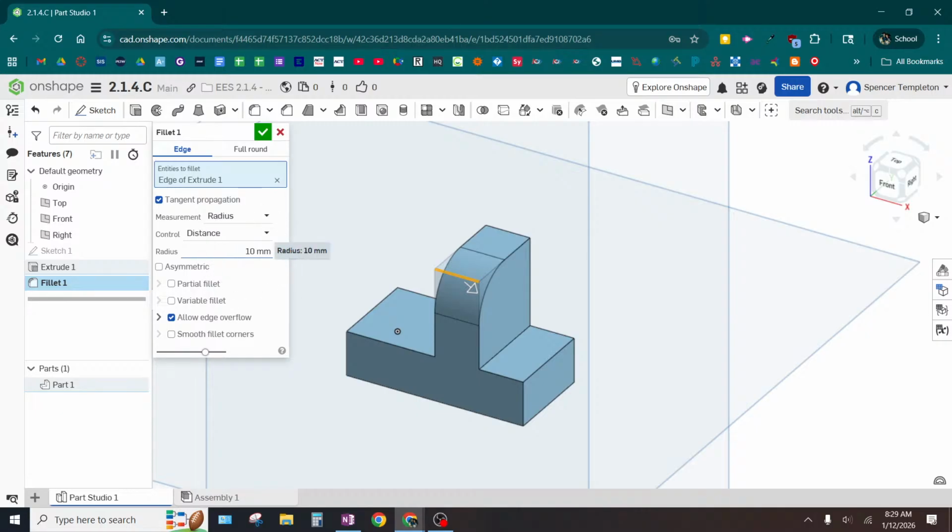Very easy. Now, I don't think you'll have any issues with this, but hypothetically, if the radius was a really big number, you might get an error when trying to create it, if you're trying to round something with a radius bigger than the size of the thing itself. So if this radius was much more than 20, you might run into some issues, okay? But if you put it at 10 here first, and then you click on it, that would alleviate that problem. Do you have any questions? That's a yeah. Okay, that's pretty easy.